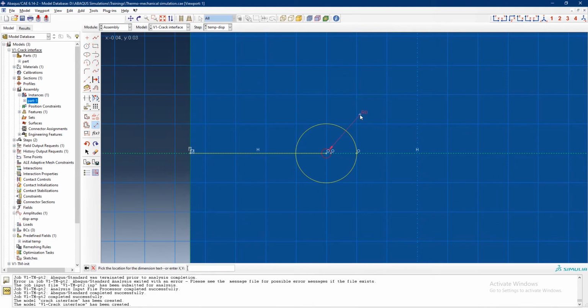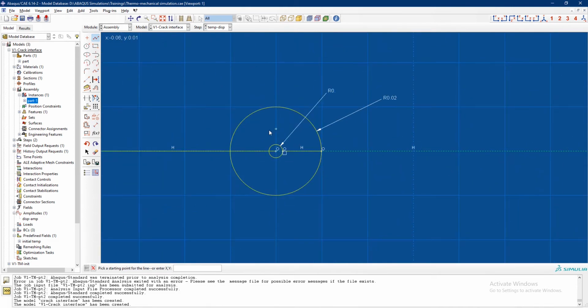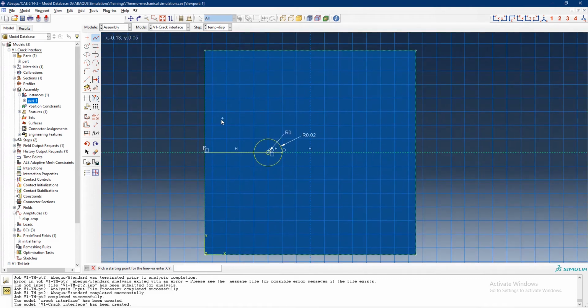Let's clean up the dimensions. It has a dimension of 0.003, and the bigger circle should be 5 to 6 times larger than that. So yeah, seems good to me. Okay, then I would also like to section it from this end to this end, so we can apply a homogeneous mesh here, and the rest seems okay to me.